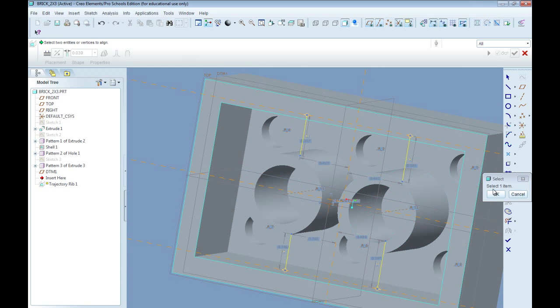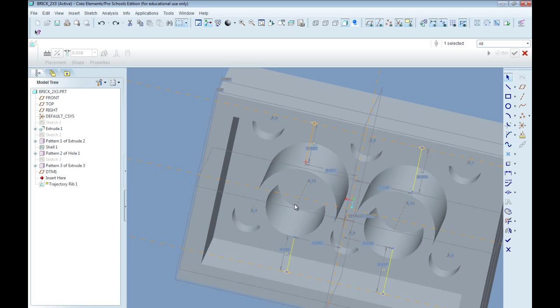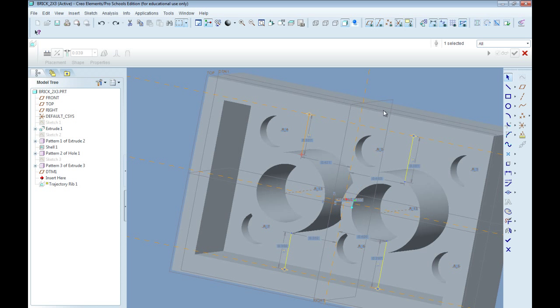And we'll create this coincident with this here. Actually, what we want, Control Z. This will be coincident, sorry, with the, let's see, our surface doesn't work. Alright. So for now, we want this point to be coincident, not with the tangent, but just coincident with the outside surface here.